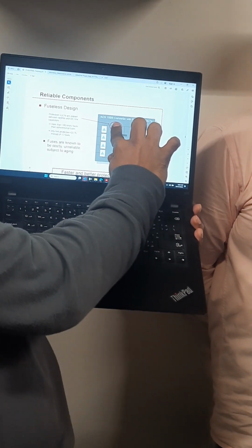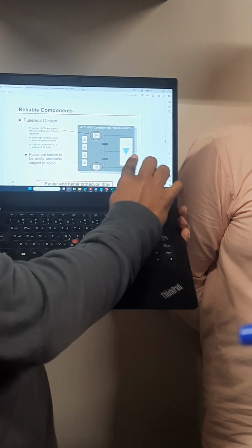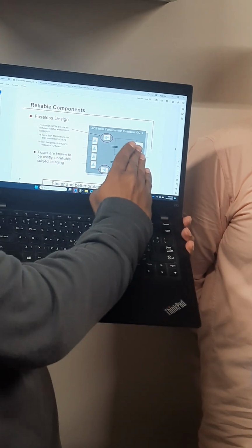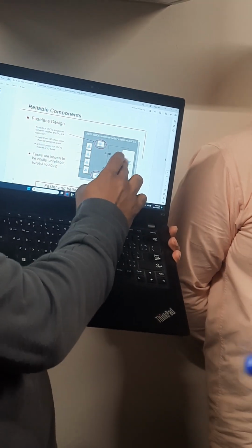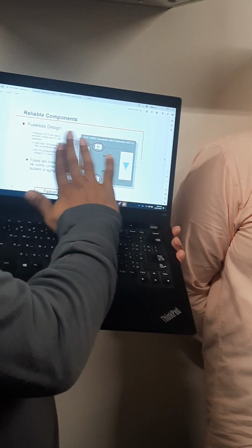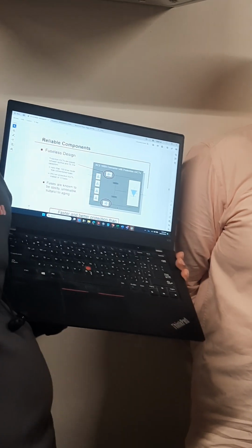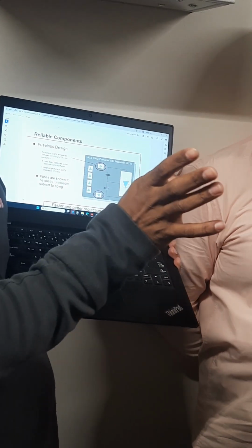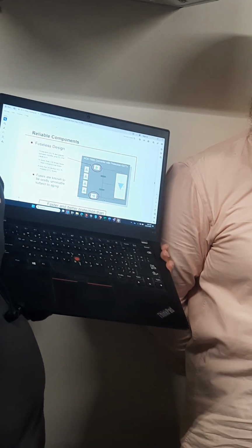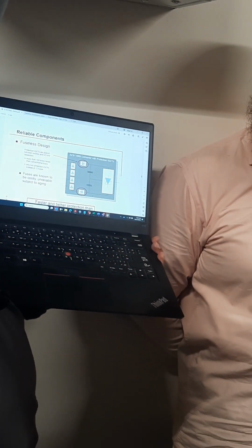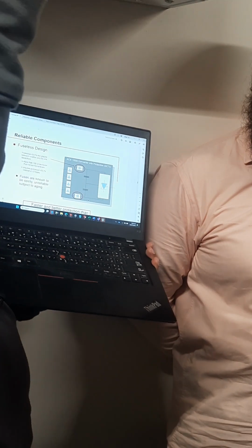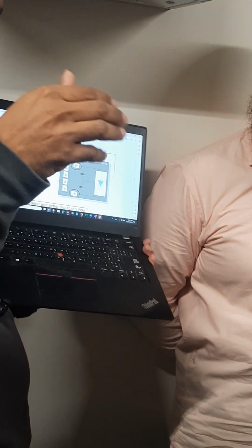Instead of a fuse unit, we have installed the protection IGCT here, and the inverter section is on this side. So this is the general structure of this drive. Here we have two types of drive. One is with the external transformer; there are two transformers in the same drive. Both are supplied from the same breaker, with 11 kV coming in.